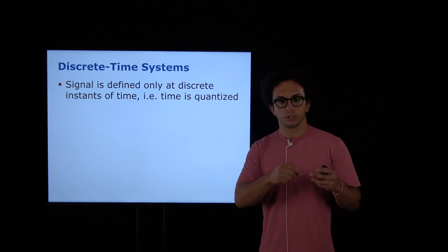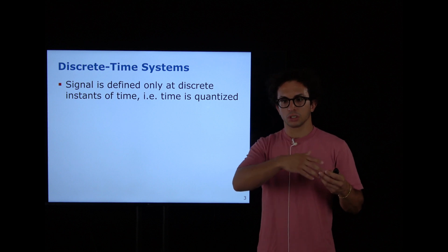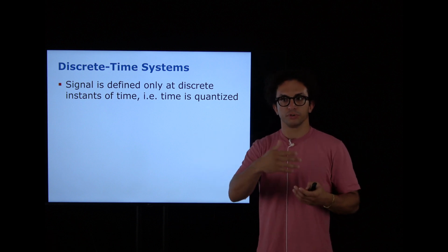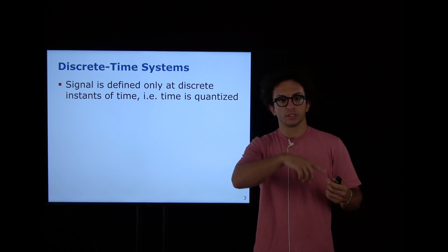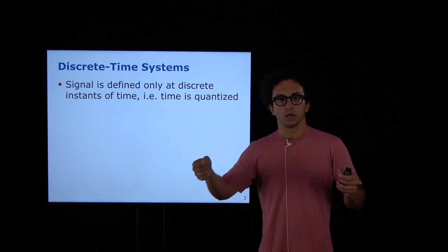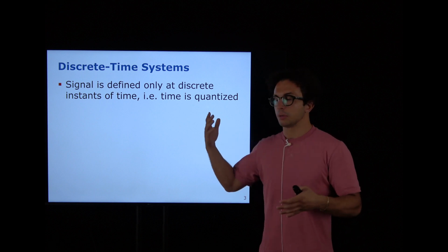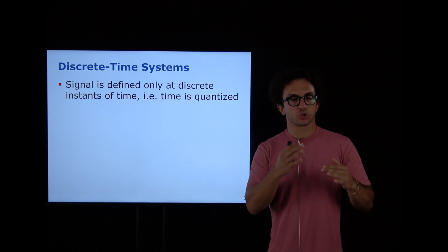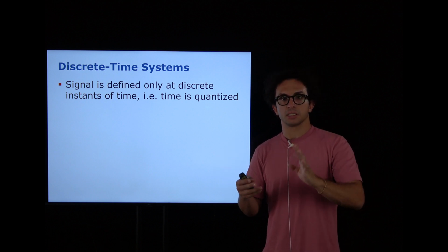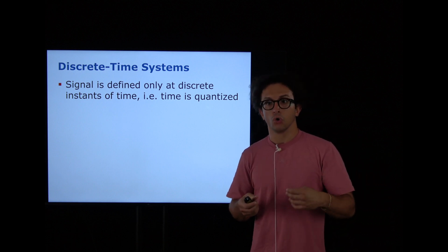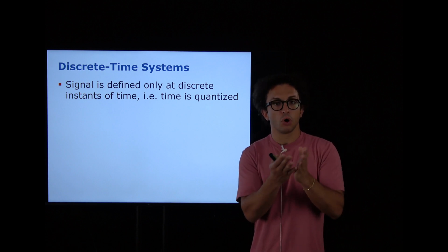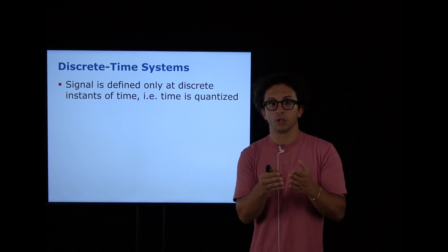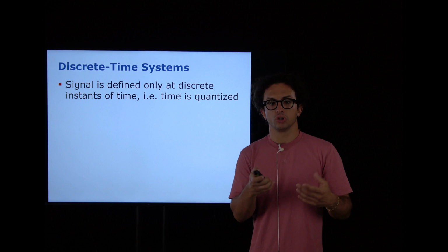The time axis that so far was continuous, so we were having this curve with dense values. For example, if you remember the curve of the evolution, where we had this overshoot, transient and steady state, there was no sampling. Now the time is quantized, so it's discrete, and we will have to look at it like a sort of grid. So there are some time instances, which is, for example, when the sensor is able to read, or when the actuator is able to give something, which can be small, like this time that we need to wait before one sample and the next one can be very, very small, but it's never zero, it's never continuous.